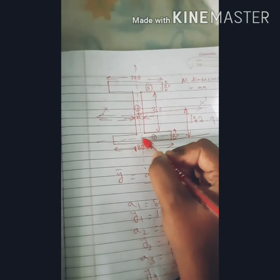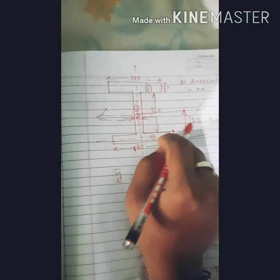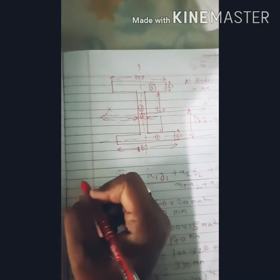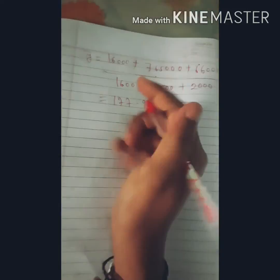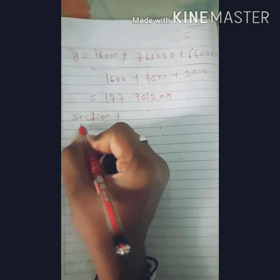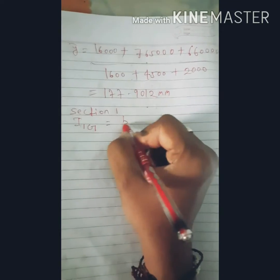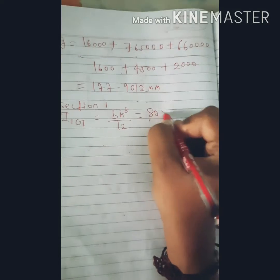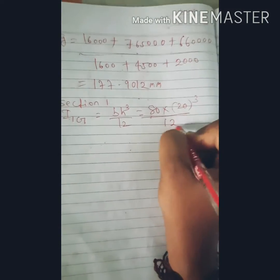We know that the moment of inertia of a rectangle along its CG, along its x-axis, is bh cube by 12. So for section 1, I1g equals 80 into 20 whole cube divided by 12.